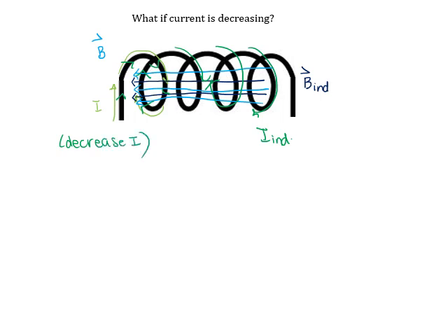Okay, what does that mean about the charge and the change in potential? Remember, moving positive charge is the same as current. So if the current flows from the left end towards the right end, positive charge is going to build up on the right end. So the right end is going to end up at high potential, and our left end would be at a lower potential. That would be our negative end. We'd have a potential difference delta V over the two ends of that inductor.